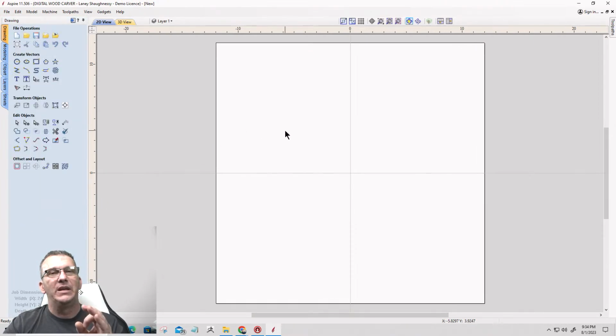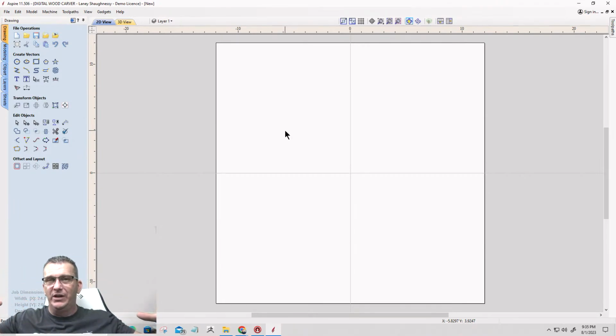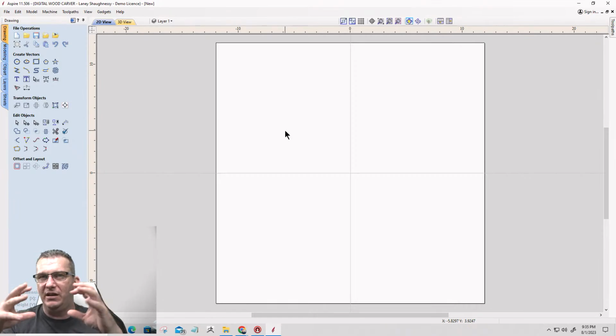Now, when you purchase models, or models that come with the software, this is important. You want to try to purchase models from a reliable source where the resolution of the model is of high quality. The model is created of a mesh and triangulations. So there are extrusions and triangulations, and then there's a mesh, a skin of these little triangulations put over it, and there could be thousands and thousands and millions of triangulations, depending on how high resolution the image is. But some models are called low poly models, meaning they're low resolution.